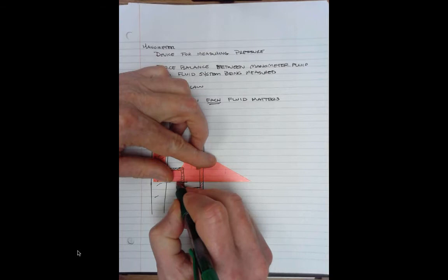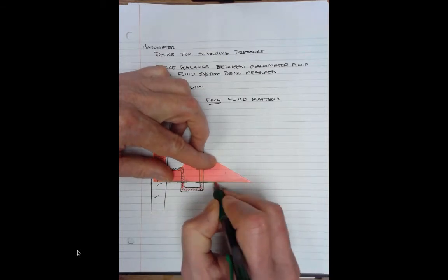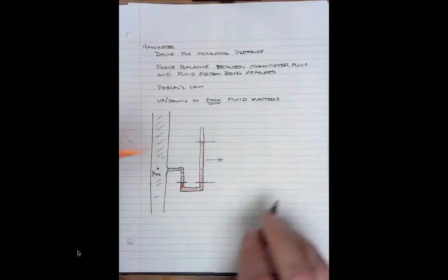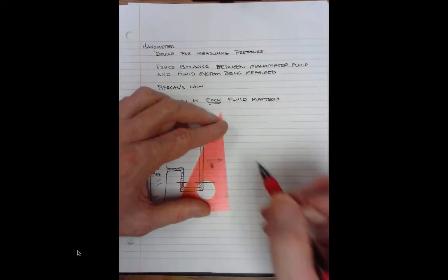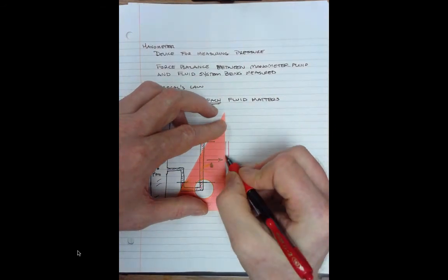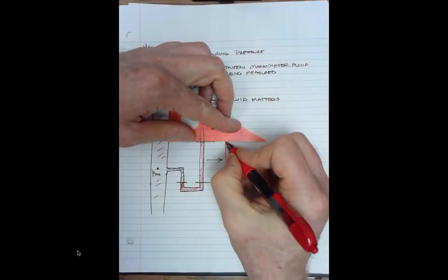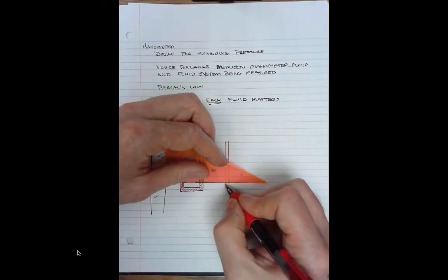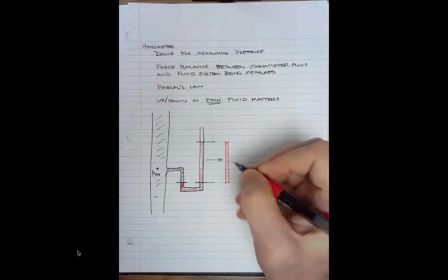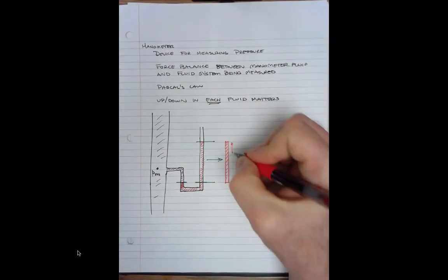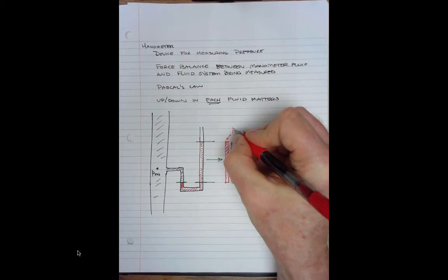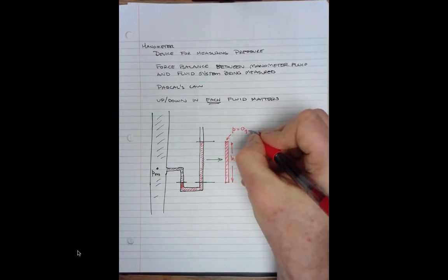And so we can figure out the pressure at this green line is simply whatever force per unit area this column of red fluid would make. So that's H units tall. Assume at the top P equals 0 gauge.